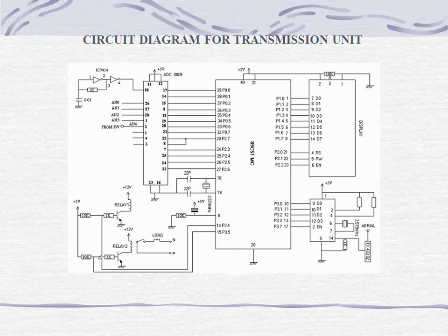The entire design is based upon the microcontroller 16F877, and the RMS value of the secondary voltage of the transformer located on the distribution side is to be monitored. Further, if necessary, you may extend this module for monitoring the power factor, reactive power and active power.